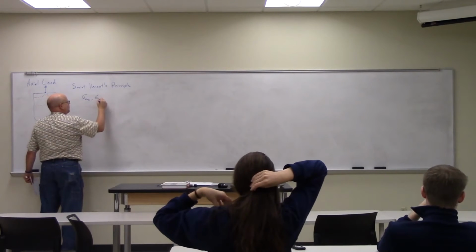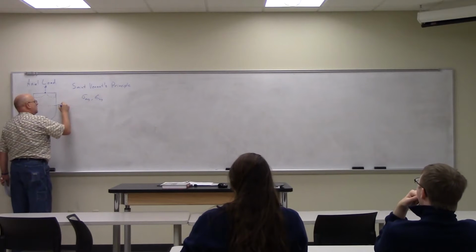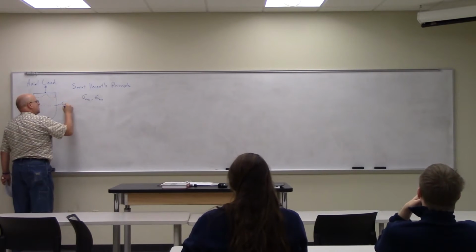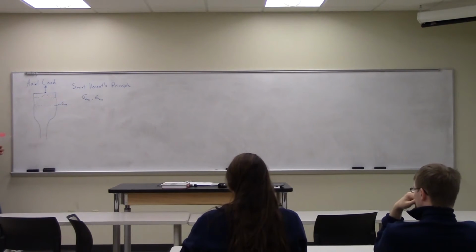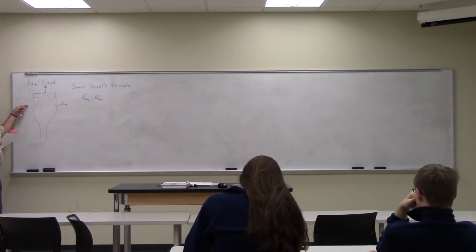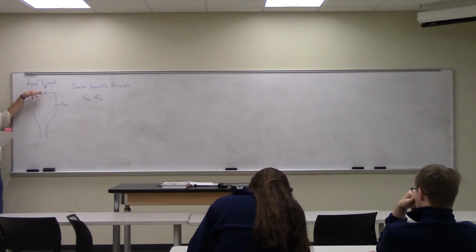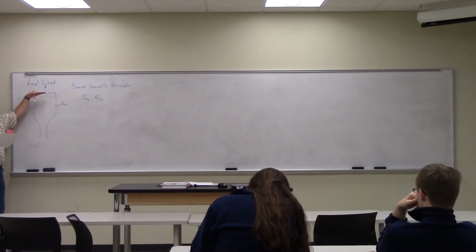So for us, we're going to focus on the average stress and strain. So this is the average stress distribution. We're going to focus on regions where we've achieved this average distribution. We're not going to work, for the most part, so close to the points of load application that we have these non-uniformities. We're going to take advantage of St. Venant's principle, and we're going to be working in this region down here.